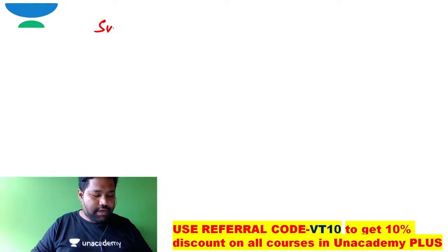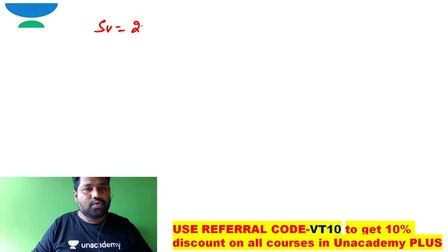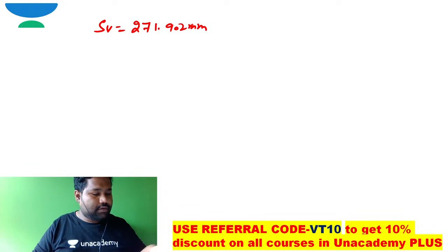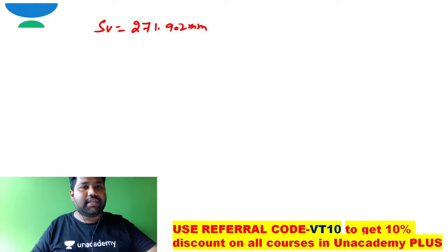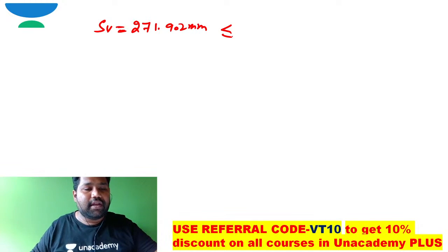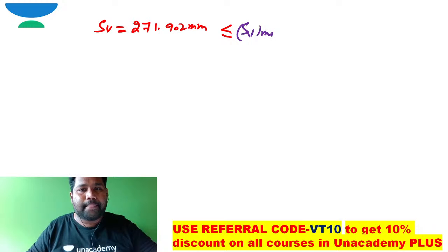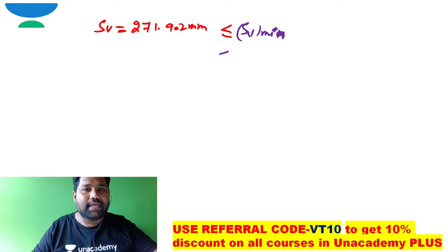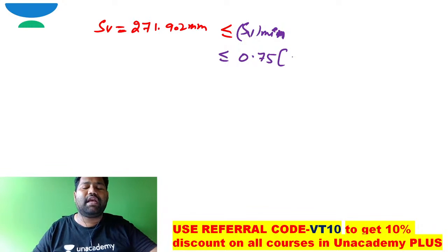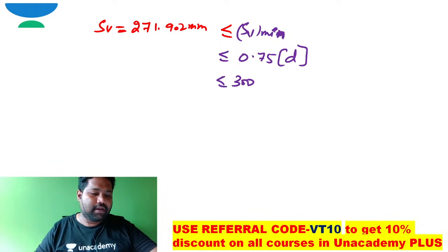So if I work out, SV is equal to 271.902 millimeter, right? But if you understand, this SV should be less than or equal to the minimum shear reinforcement spacing. What is the minimum shear reinforcement for this problem? This should be less than or equal to 0.75 times of effective depth. But the effective depth is D, be less than or equal to 300 millimeter, right?